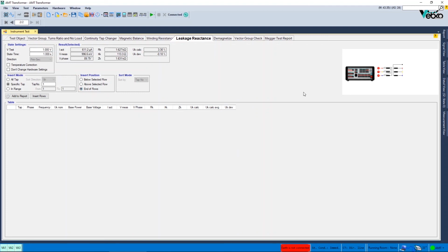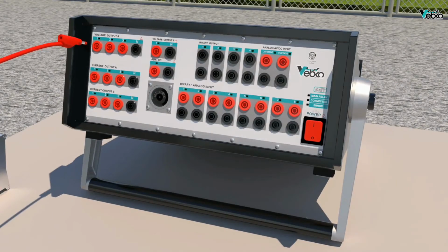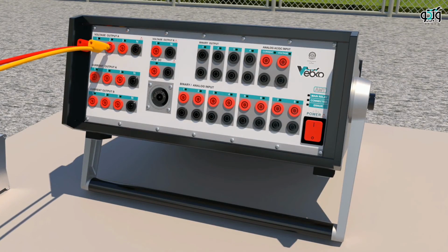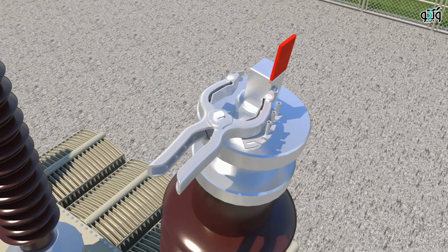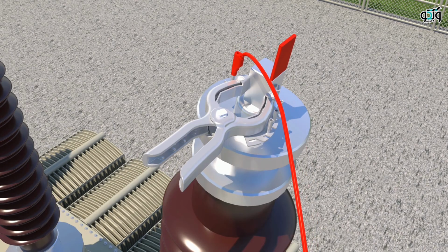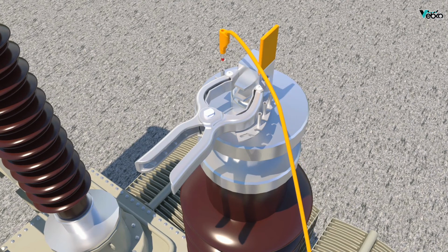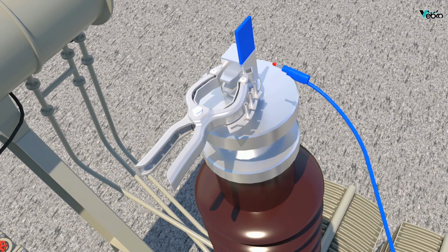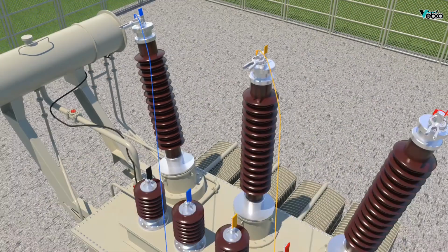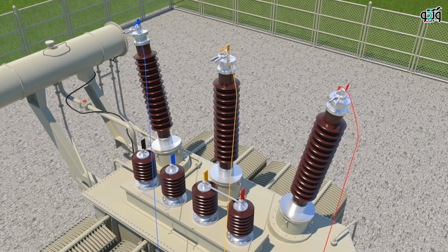After performing the wiring shown in the figure, it should only be noted that if the secondary winding of a transformer is YN, the secondary neutral should not be connected to the other phases.